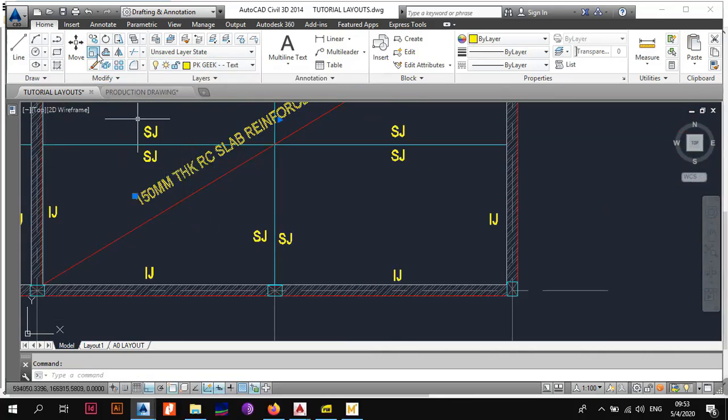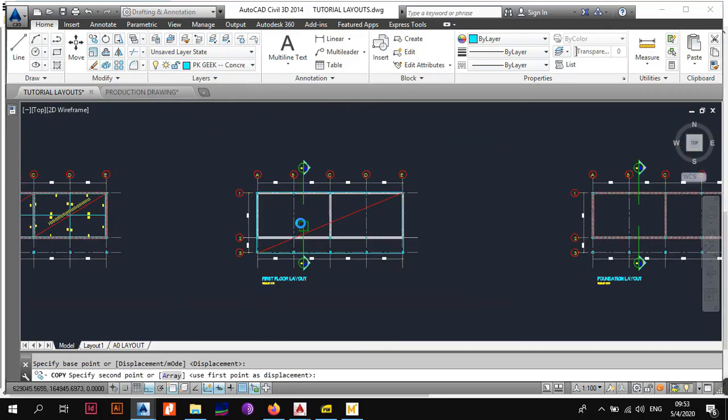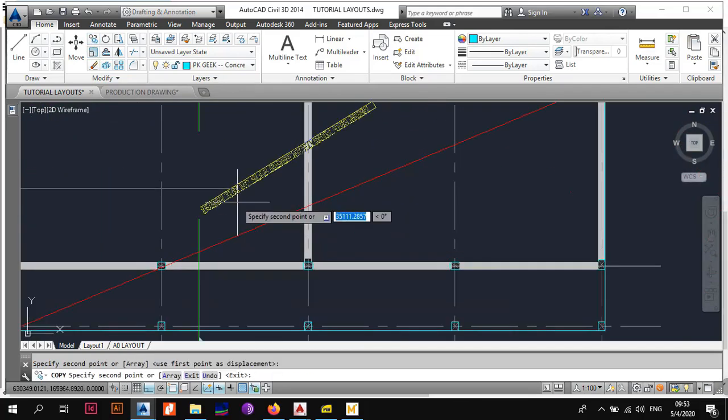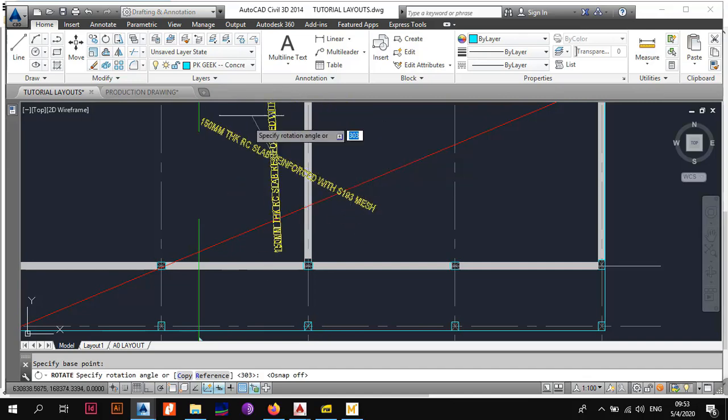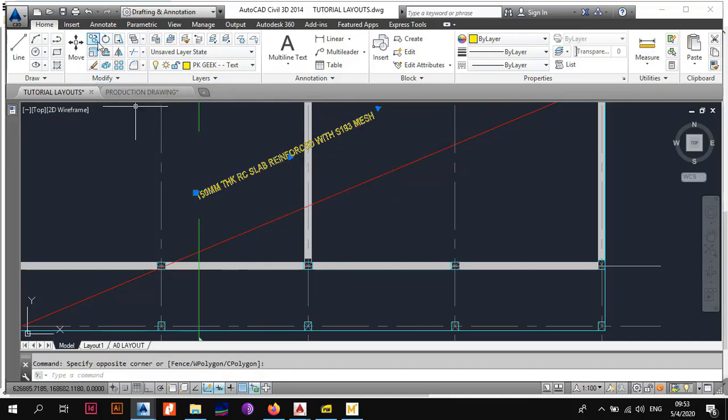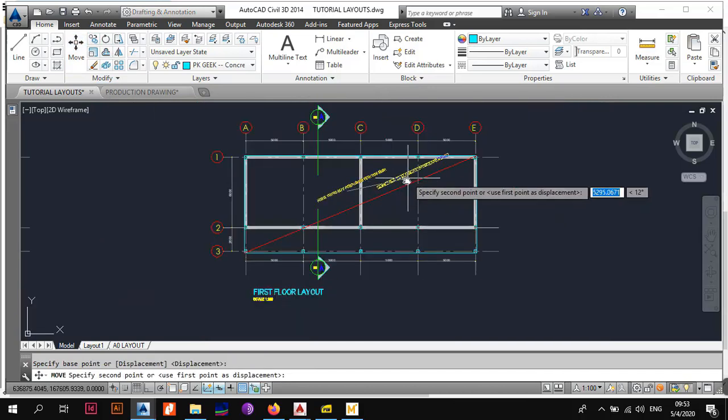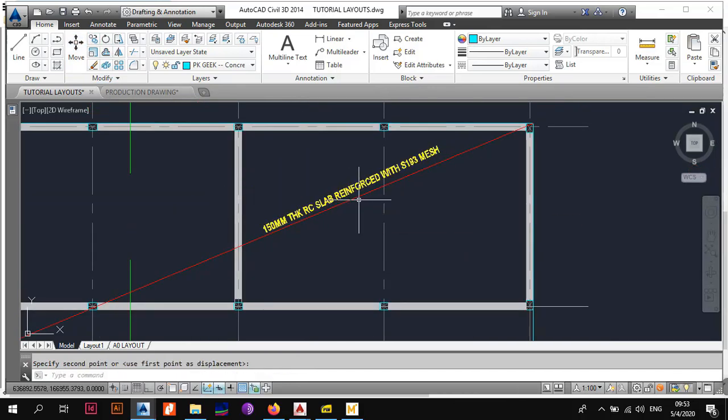And also we need to annotate and represent that it is definitely a slab. So what we're going to do is now just paste this there and then rotate it nicely, so that let's turn off F8 for a while. Alright, so I think we also need to turn off F3 so that it doesn't snap to unwanted places. I think this is okay. Let's just move it so it doesn't interact with the hatch.